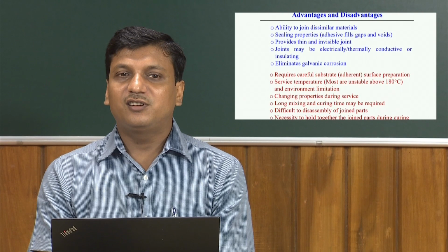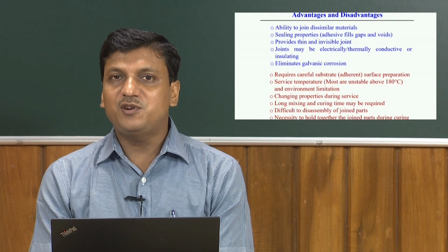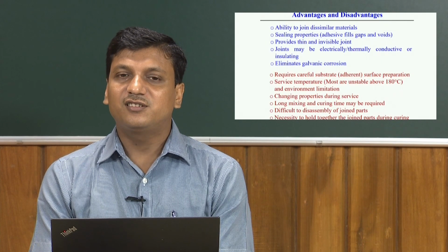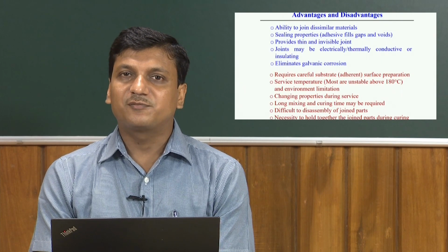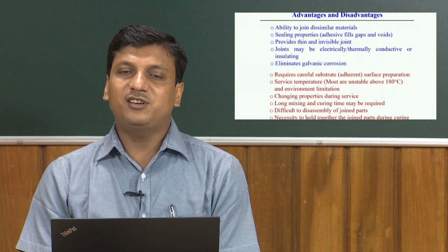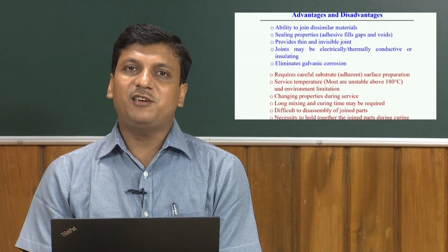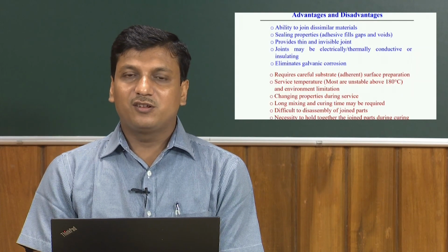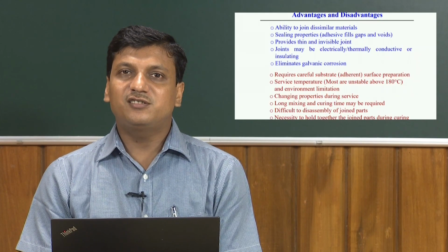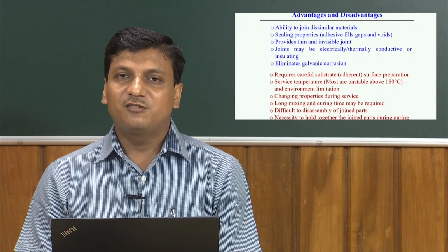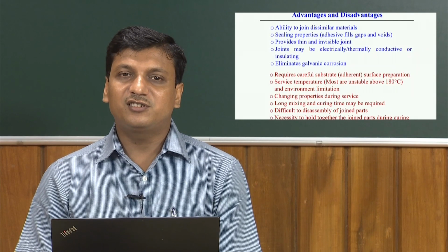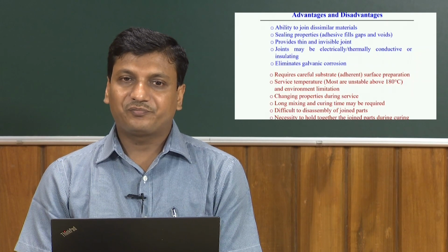Service temperature has some limitation, in most cases it is below 180 degree centigrade, and also there is an environment limitation. The environment also affects the service life of an adhesive joint, but the main limitation is the application temperature. Above 180 degree centigrade the adhesive joint basically fails. So, that is the important limitation of this type of joining.